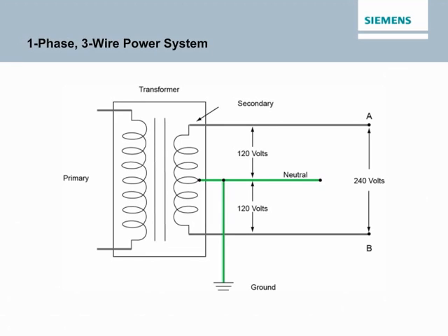Panel boards receive power from a variety of sources. For example, a downstream panel board typically receives power from an upstream panel board or switchboard. However, power for the distribution system originates from a utility power company. Power from the utility is stepped down through a transformer for distribution to a facility. There are a number of ways that the transformer's secondary windings providing service may be configured. In order to properly select a panel board, you need to understand which voltage and system will be connected.